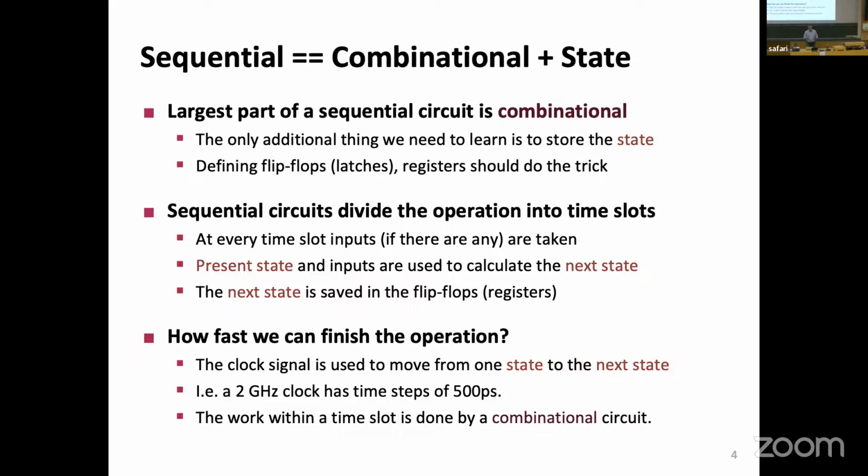Now, once these have memorized the input and copied it to the output, the combinational logic all of a sudden will get new inputs. And they say, oh my God, I have to do something. So they will be thinking about it, AND gates, OR gates, inverters, things changing around and additions happening, carries propagating. And this will take a while. And then at the end of it, there is another state holding element that is ready to memorize it.